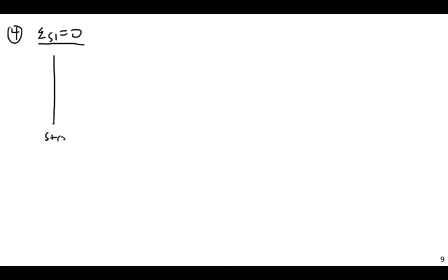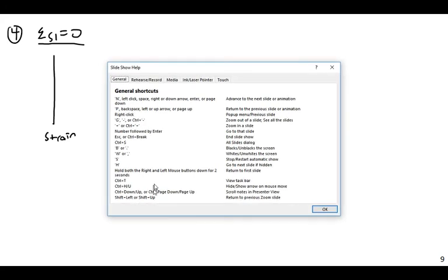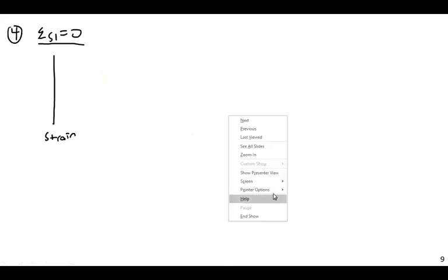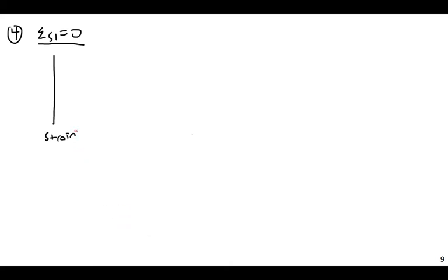So we have strain, and so essentially I'm assuming here, this would be the case where the neutral axis is actually at the tension steel. So I would have something like this. And this seems odd at first. How would you ever have 0? You might think, how in the world would I ever have 0 strain in the tension steel?